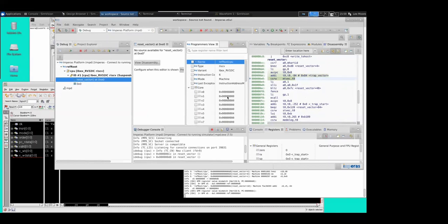And we have a full software debugger here that allows us to go and look at the code that's executing. We can look at the source code if there was source code rather than assembler in here. And we can also go and look at all of the internals, including not only the core registers, but things like the machine control state registers, recording information such as internally held state for what mode we're operating in or what the last exception was that occurred.